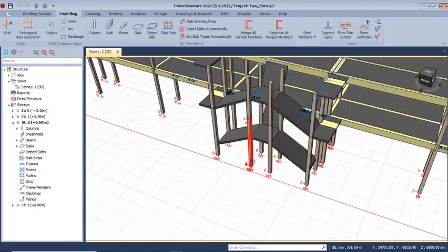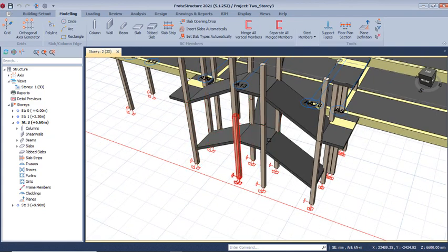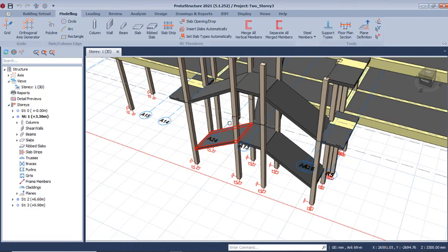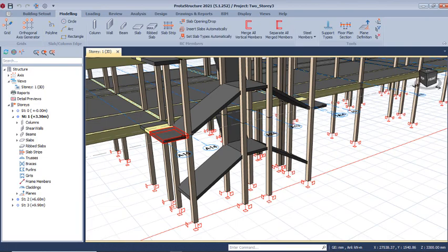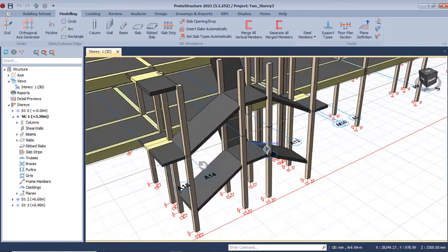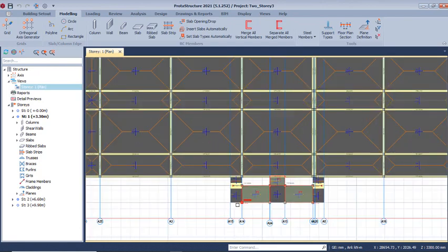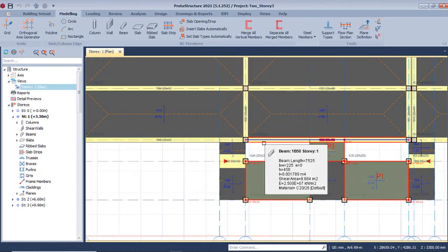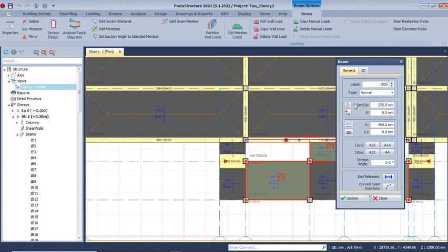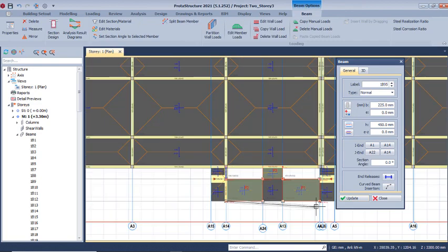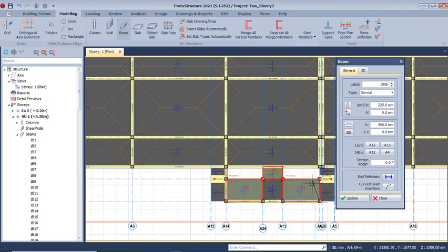Also we will be having beams at this point, story 1. So you navigate to story 1 right there. We need a beam here that will connect this point and this point, because this is going to rest on the beams. So that is what we are going to be considering. We will navigate to the plan view of story 1 right there, just like this. We can still put a fix it while on that view. Then you click on that property, and you use the property of this beam. So I will need a beam here using that property. So we have something like this. We still have a beam that will run from that point to this point, just like this. And then we have another one here.